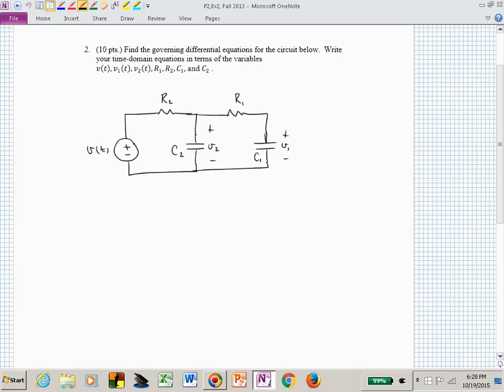With the ladder, you can follow your analysis as you go, and the logic should sort of make sense. And at the very end, you've just gradually found the entire solution. So it's sort of clean that way. It'll get even cleaner when we leave the time domain and put this circuit into the frequency domain. To begin with, when we convert all the L's to sL's, all the C's to 1 over sC's, and the R's we leave as R's, then we're dealing with Chapter 13.